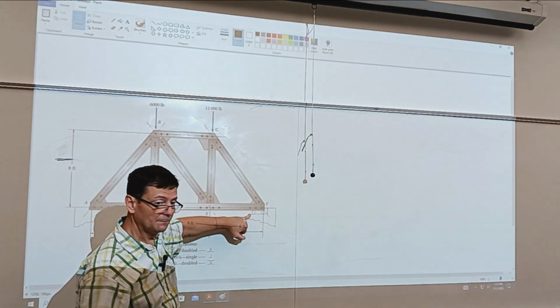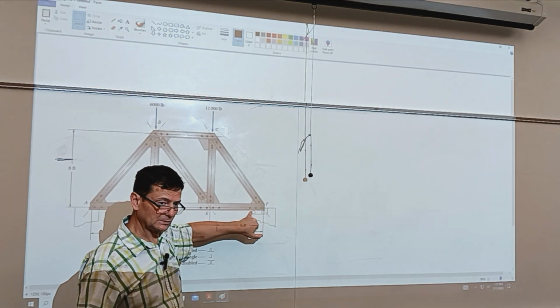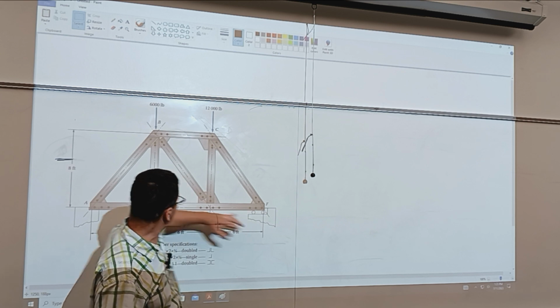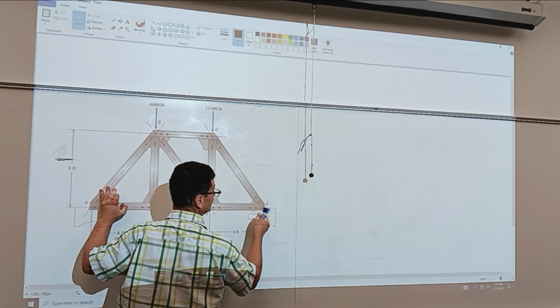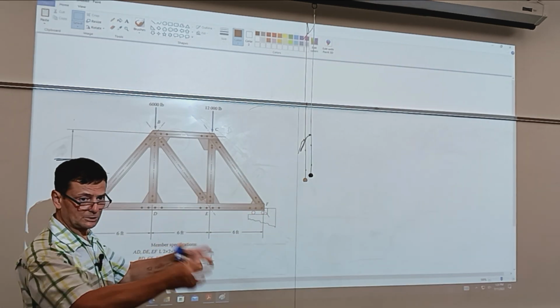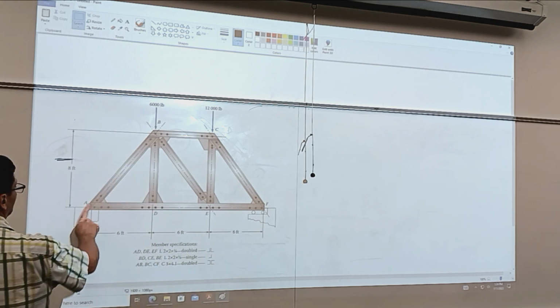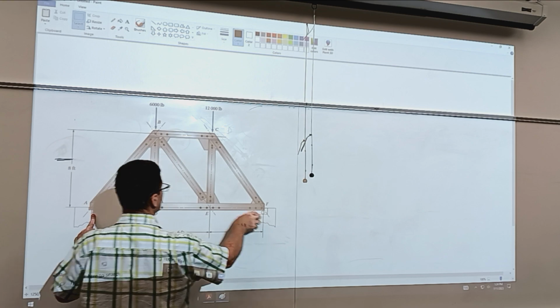There are bridges. Harbor Bridge. I took a picture of the rollers. I could show it to you, could project it. So in order to allow for thermal expansion, these ends are not fixed, but are put on rollers to allow for a length increase.